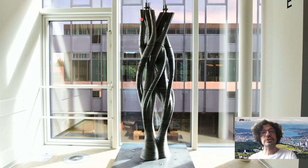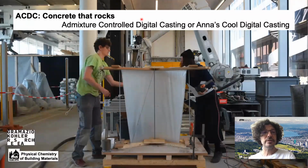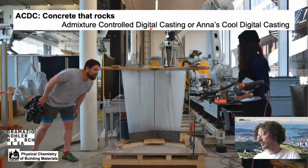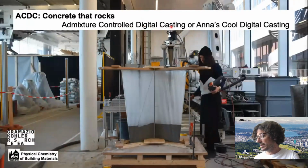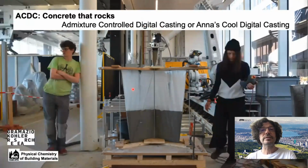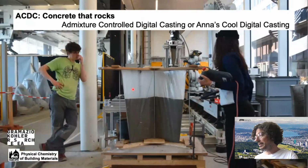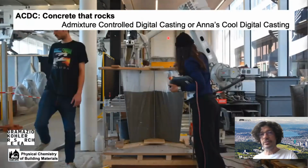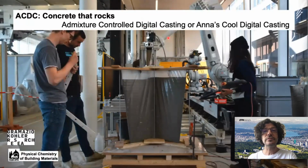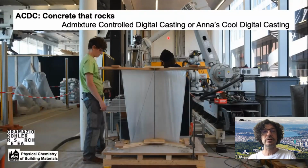And just about as cheap as it gets is a plastic foil from the supermarket. This video shows you the process that we refer to as admixture controlled digital casting. And what you see is that the concrete gets cast into this plastic formwork, which does not deform. It does not deform because there is an accelerator added here in the nozzle, which helps the material, as soon as it is deposited, to stiffen enough and avoid any substantial hydrostatic pressure from developing.